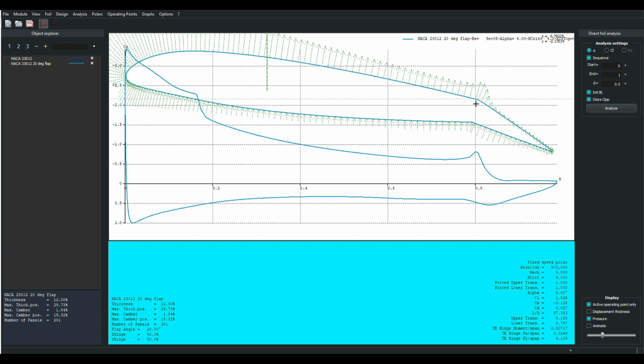And the way that Xfoil sets these up, you can set the hinge line so that it's right in the middle here, and that's analogous to what I have on my wing in terms of the ball and socket joint, that it's not hinged on the upper surface, not on the lower surface, but right in the middle, which is traditional for general aviation aircraft. It's a nice, efficient configuration and generally disrupts the flow the least amount. It's also one of the more complicated ones to build.